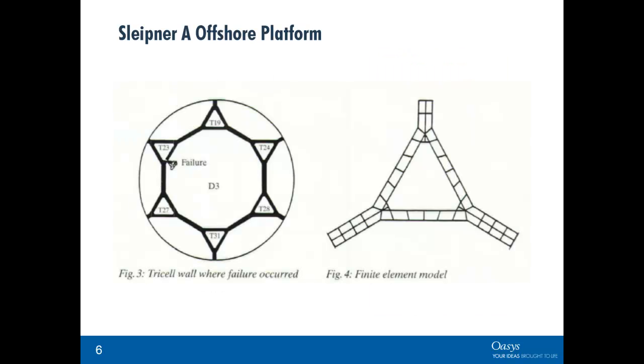Unfortunately, it went wrong. The cells there, you can see the cell in the middle must be filled with air initially, or seawater and oil, and the triangular areas between were open to the sea, which means that at full load they should be designed for a depth of 82 meters head of water.